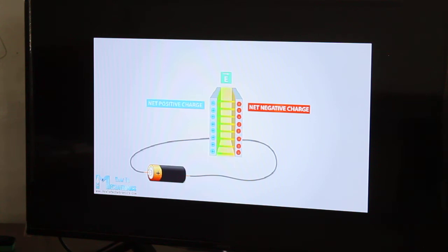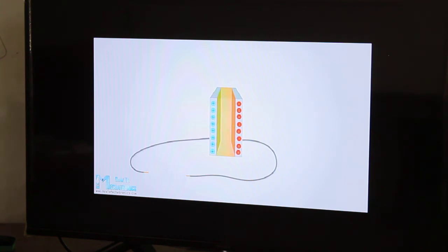Decoupling capacitors are often used along with integrated circuits, and they are placed between the power source and the ground of the IC. Their job is to filter any noise in the power supply, like voltage ripples, which occur when the power supply for a very short period of time drops its voltage, or when a portion of a circuit is switched, causing fluctuations in the power supply. At that moment, when the voltage drop occurs, the capacitor will temporarily act as a power supply, bypassing the main power supply.